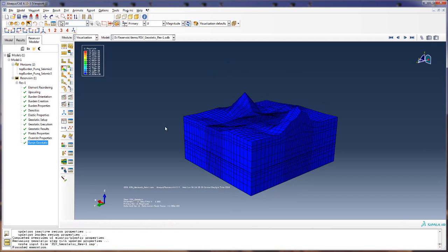And then from here we have the model ready to run, and we can set up within Abaqus CAE an analysis to read from the output database. We could read histories of pore pressures and things like that to calculate a subsidence history. So anyway, this has been just a quick demo of the Reservoir Modeler.